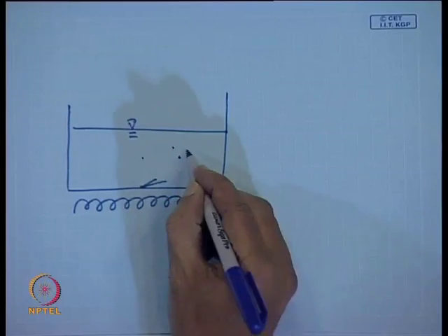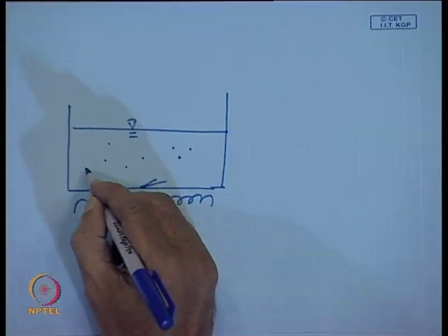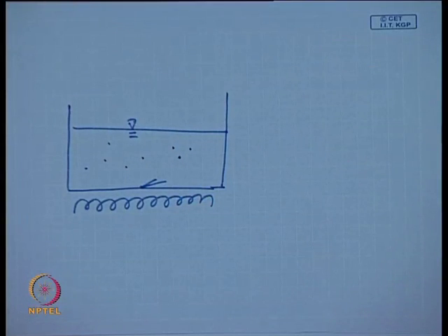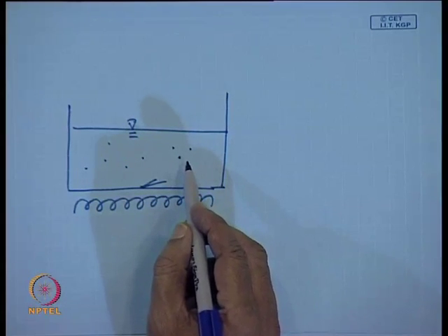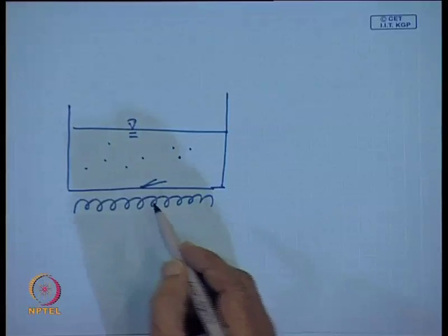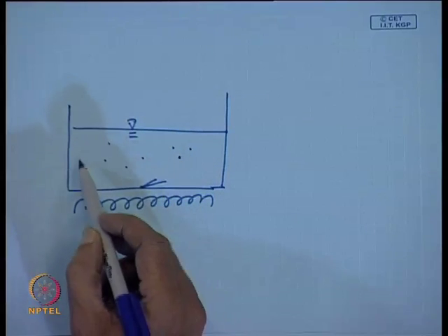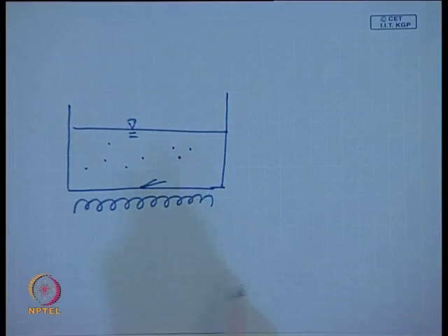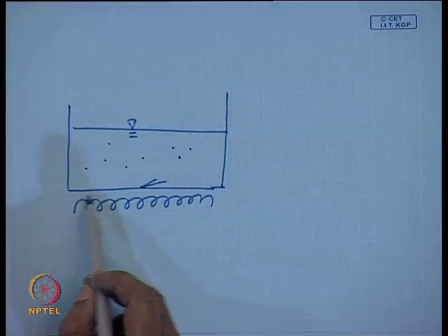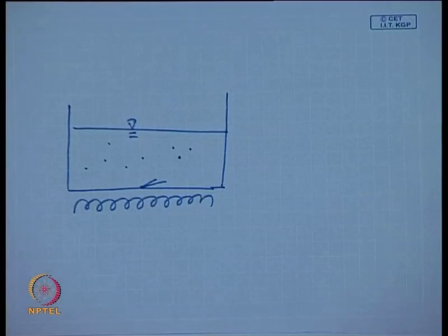The fallacy lies in the fact that dissolved gases, or for that matter the small suspended particles in the bulk of the liquid, though they help reducing the degree of superheat needed for boiling, they do not play the main role for boiling when we are considering a system like this. Here the main role is played by the surface of the container.